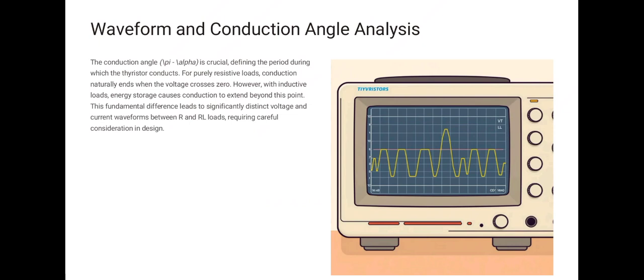Waveforms and conduction angle analysis. The conduction angle is crucial, defining the period during which the thyristor conducts. For purely resistive loads, conduction naturally ends when the voltage crosses zero. However, with inductive loads, energy storage causes conduction to extend beyond this point. This fundamental difference leads to significantly distinct voltage and current waveforms between R and RL loads, requiring careful consideration in design.